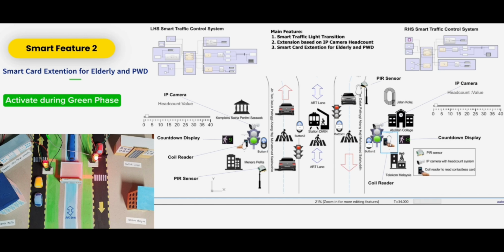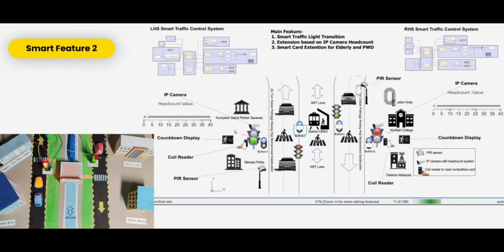At the green phase, it directly increases the current green. During the flashing green, the activation of the card will not give any extension for the current green interval.